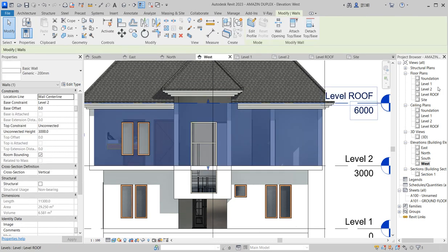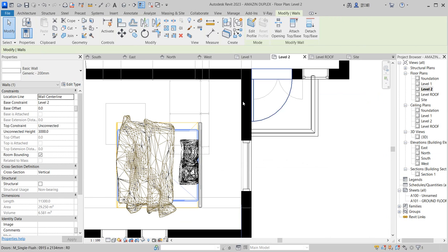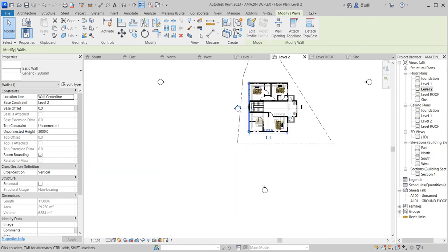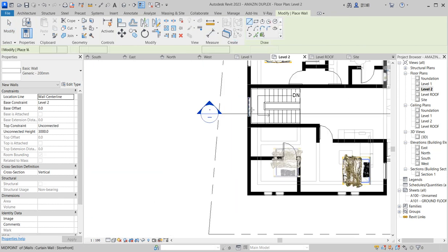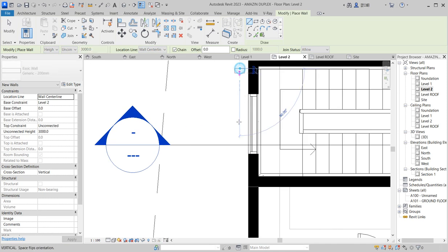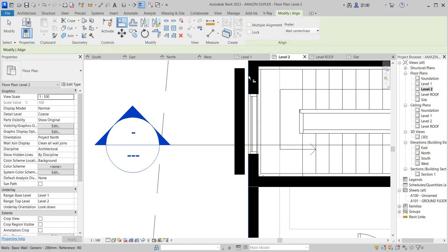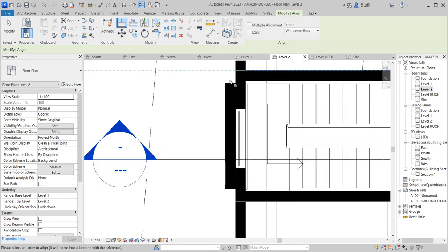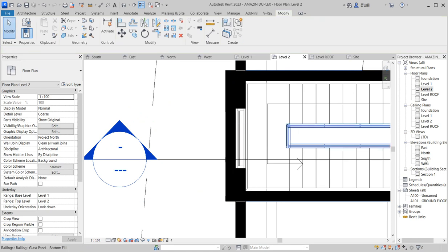I'm going to lay a wall on the wall so that the beautiful aspect of that will be covered. Click here on level 2 and say create similar. You create similar, you lay one wall on this one. It's going to be a double wall at the back, but this one is going to be a design pattern because it's not going to be flush like that one.